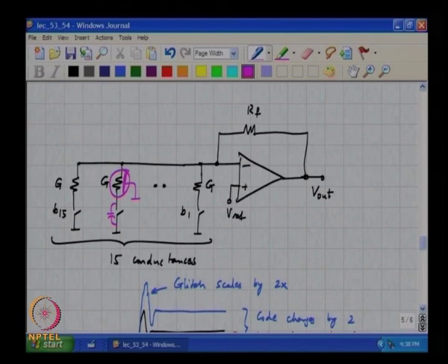So, the moment you turn the switch on, it is not as if these capacitors, which are all charged to Vref before, if the switch is open, right, all these tiny capacitors along this conductance will have been charged to Vref. Now, when you suddenly close the switch, this potential is supposed to go to ground. So, the capacitor voltages which were all Vref before must correspondingly go down to some other values depending on their position along this resistor, right. That obviously cannot happen instantaneously, which means that there is speed limitation to how quickly you can make the output waveform switch, alright.